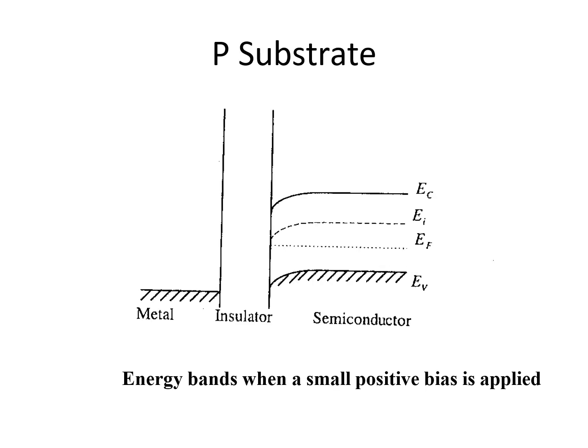When a small positive voltage is applied, you look at it, automatically the energy band diagram is in the reversed state. The Fermi level of the metal is coming down. So you look at the shape of the energy band diagram when a small positive voltage is applied.